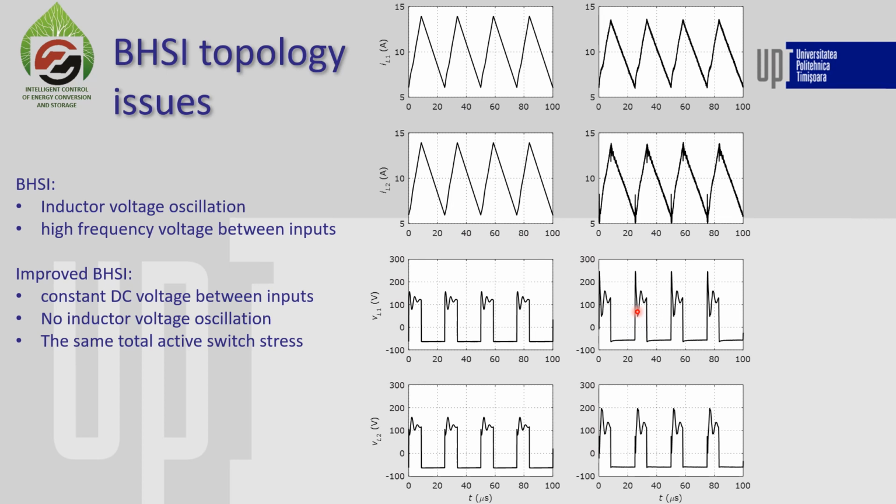And this might be an aspect which we expected. We see here that the oscillations are higher in the experiment, and they are a bit difficult to actually predict precisely because these oscillations appear because of the parasitic capacitors of the switches, which we know vary pretty much with the voltage on the transistors.